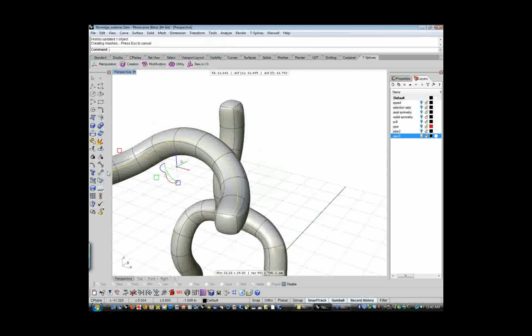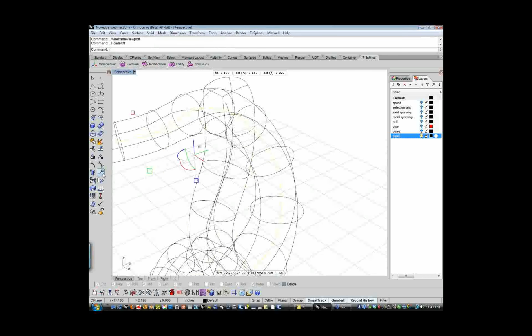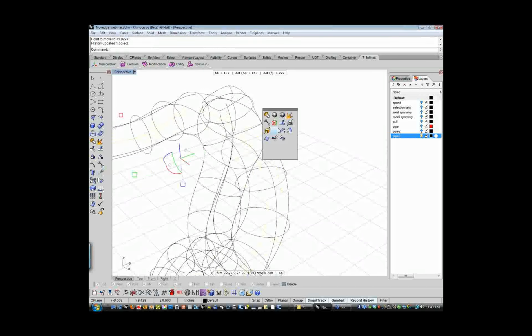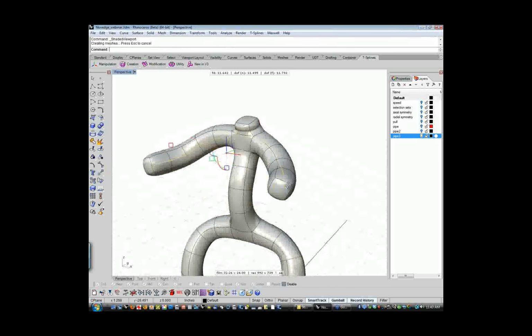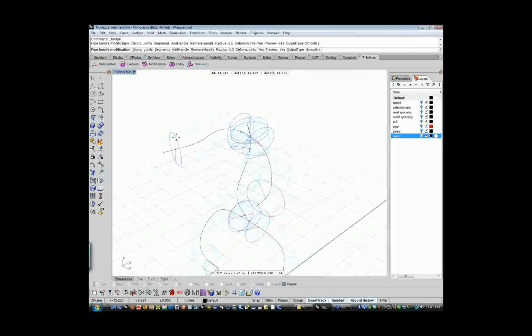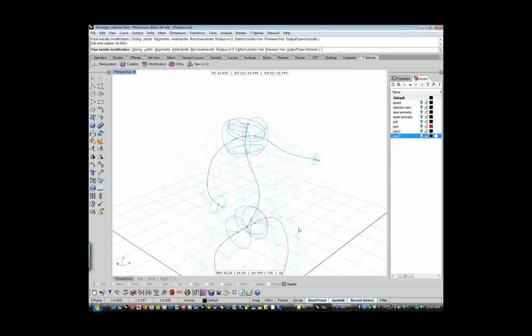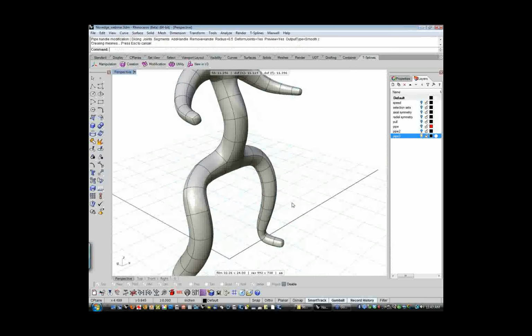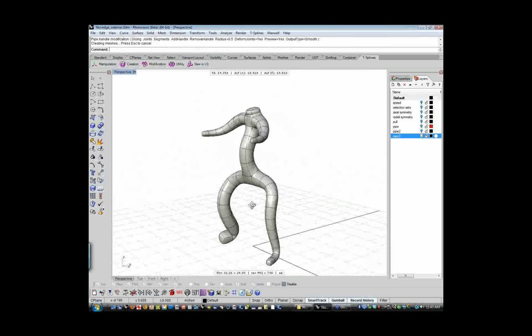One other cool thing is you can re-enter that pipe command. If you make the pipe command and then play around with your model, you can re-enter the pipe command by selecting that line, and then selecting the T-spline model. There you go. If you enter the pipe command and select the model first, then it will remember your last settings. You can see how it went back in and remembered you had different radiuses there. So you can come back in and change the radius later without having to go back to the curve. That's kind of cool. Jump back into the model and do your modifications like that instead of dragging control points. Oh, you big thunder stealer. That's awesome. I love that.